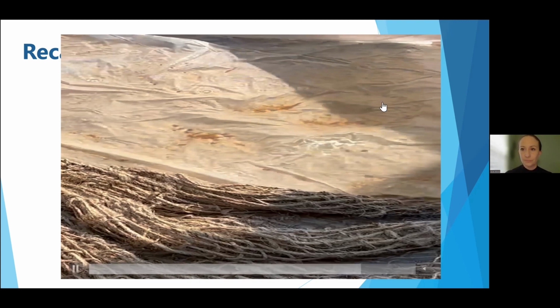Okay. Here's another question. How should recovered PAMs and sediment and jute netting be disposed of? Sure. So it depends on where you are. Again, as I mentioned, the PAM is not a hazardous material. And a lot of times, if you have a jute matting that has both PAM and sediment that it's become saturated with, you can just layer more on top of it to keep collecting those particles.